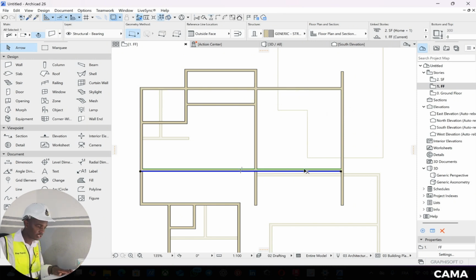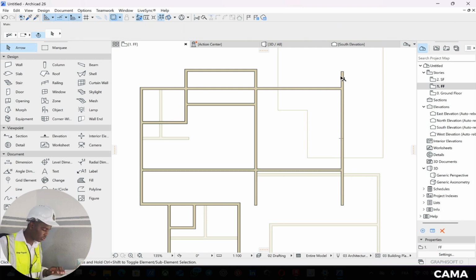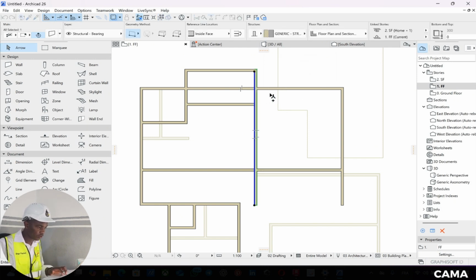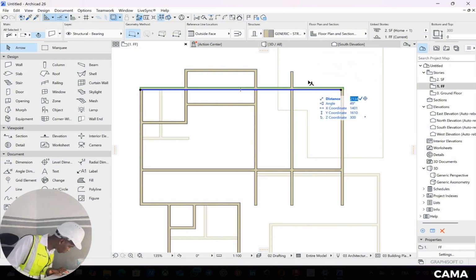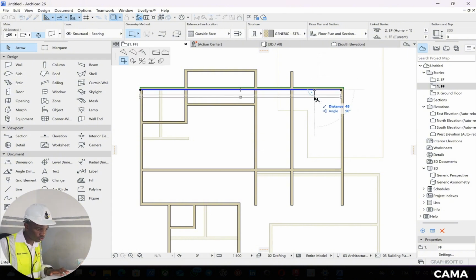Oh, it's even at the same size. Right here, you extend this line. That's it. This is your room 2, bedroom 2. You delete this unnecessary part. That's bedroom 2. Now in bedroom 2, you need to put the bathroom. The bathroom is of size 2 by 2. That's Ctrl Shift D, 215 here. Enter. Ctrl Shift D, 215, 215. Enter.